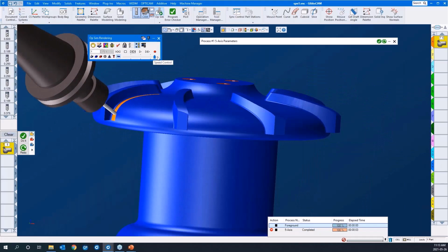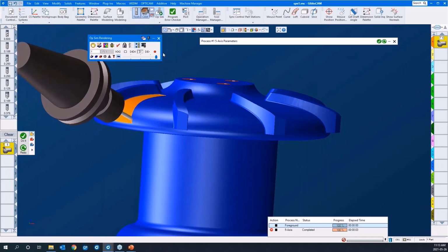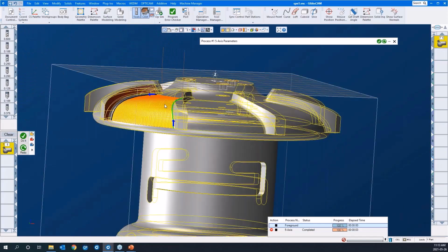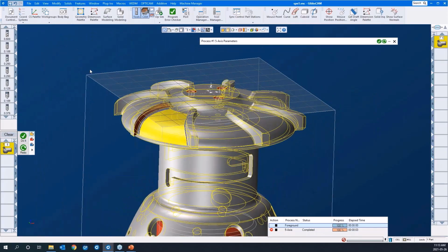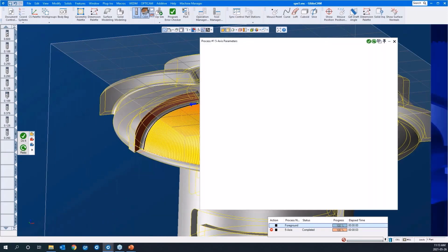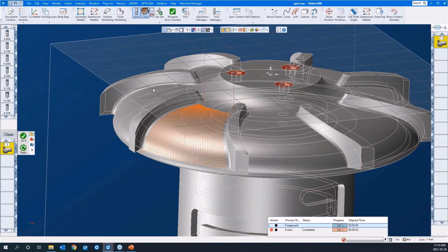Okay, and as we go through and I show you the 5-axis, I will describe some of the features available in OpSim and in machine simulation as well. Okay, so we're milling with the end of the tool here. So a lot of the 5-axis module is end milling, but there's a very important component to 5-axis, and that's side milling. Swarf milling they call it, side wall area relief feed.